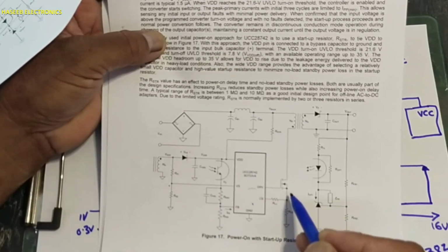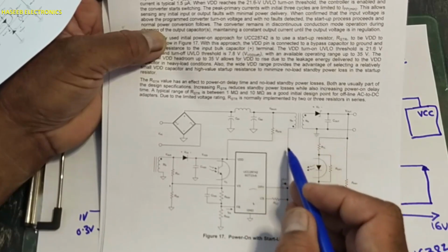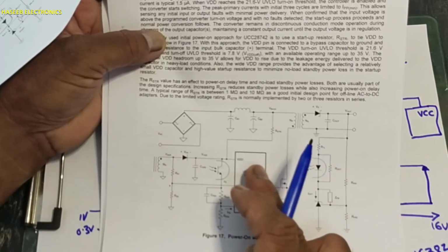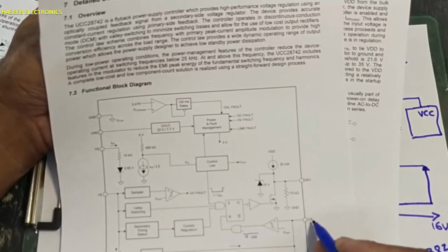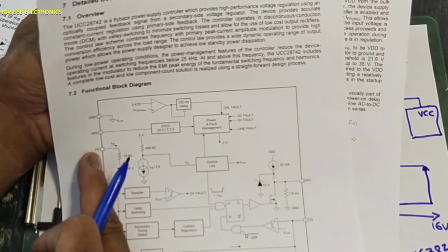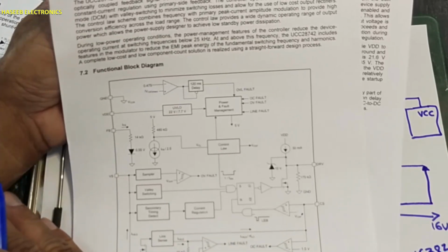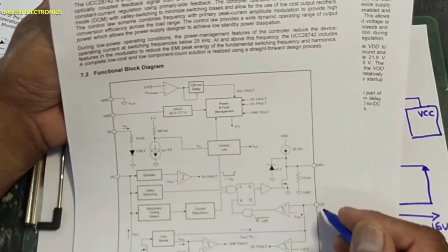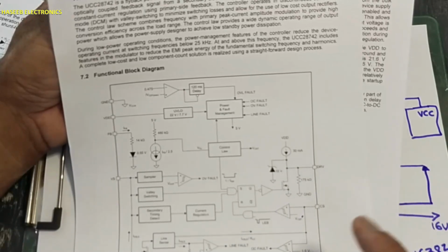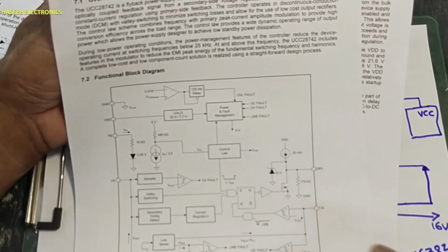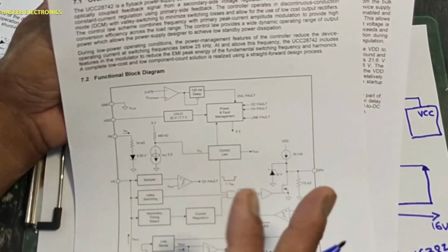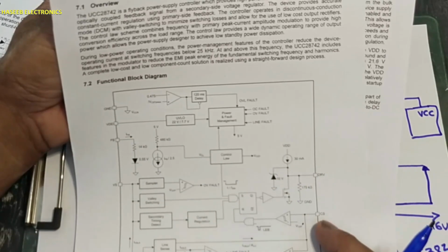When current flows in this channel, in the primary winding, it will sense the voltage dropped across this resistor at this pin. Current sense is directly coupled with feedback: how much voltage is in the output and how much current is here. In the 3842 IC, there was a 1 volt reference. Here is VCST. It has a similar function. So it will monitor 2 units at the same time, feedback and current sense.